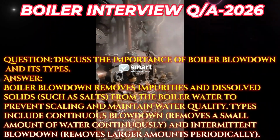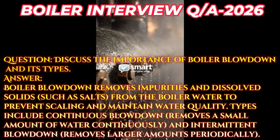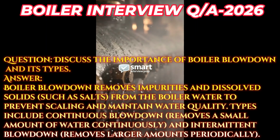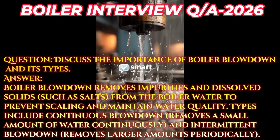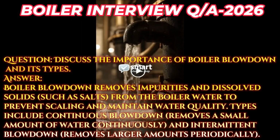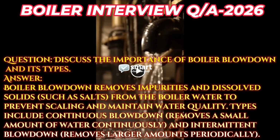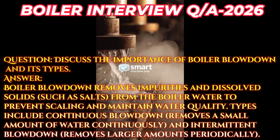Question: discuss the importance of boiler blowdown and its types. Answer: boiler blowdown removes impurities and dissolved solids, such as salts, from the boiler water to prevent scaling and maintain water quality. Types include continuous blowdown, which removes a small amount of water continuously, and intermittent blowdown, which removes larger amounts periodically.